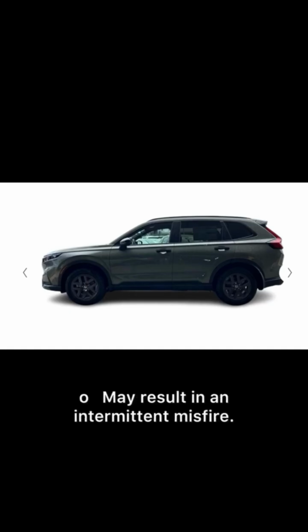13. What are the first steps in any vehicle diagnosis? Verify customer concern. Preliminary checks, visual or operational. Perform published diagnostic system checks. Check for bulletins. Module M, Exhaust Systems Master. 1. What is the purpose of the exhaust system?